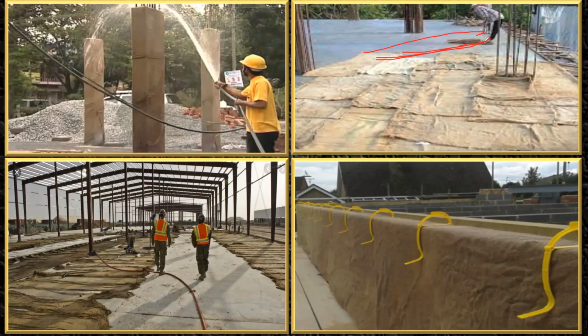If you go to the sawmill, you get that waste. If you keep that on the surface of the slab and sprinkle water, it will absorb the water, and water will remain there for a long period of time. But again, it depends on the availability of the sawdust. It's not available everywhere, and even the transportation of the sawdust is quite difficult. So we usually don't go with that.